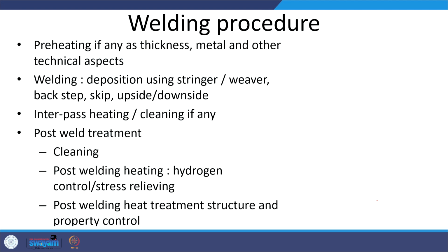Okay. Now, as far as preheating is concerned, for many metals preheating helps in a number of ways, but again it will depend upon the specific requirements. Theoretically, we prefer not to weld under the preheated condition, because it is difficult to handle the base metal during welding when it is preheated. Say, if the base metal is at 24 degrees centigrade, it is easier to handle, but if it is at 150 degrees centigrade, then we need to be very careful in the development of weld joints.